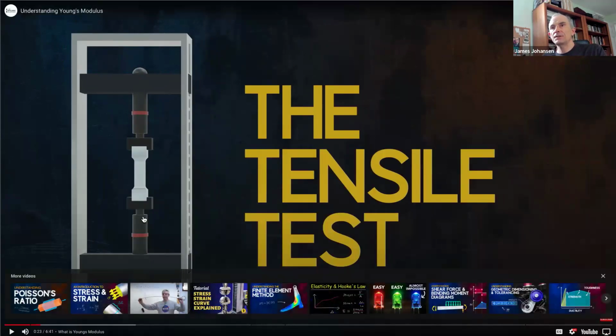The tensile test is basically you get a sample of material and you just start pulling it, and you record how much stress you have to put it under before it actually ruptures. Before that, you can see when it starts to get longer, and it varies in how much it changes over the amount of stress.